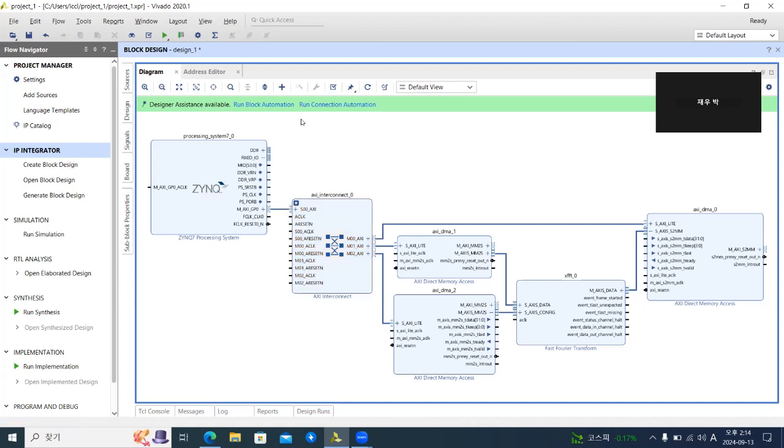Okay. So the CPU can talk to the DMAs right now. It can make requests like, hey, send some data from here to whatever, and so on. But we don't have the capability for the DMAs talking back to the CPU. They need to talk back to the CPU that, oh, we finished our job. That's why we need an extra AXI interconnect.